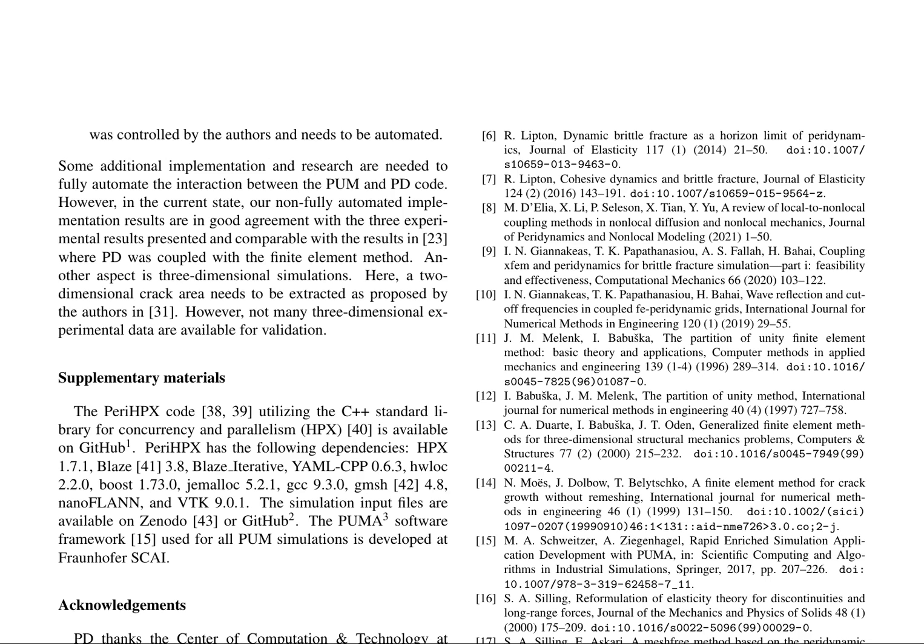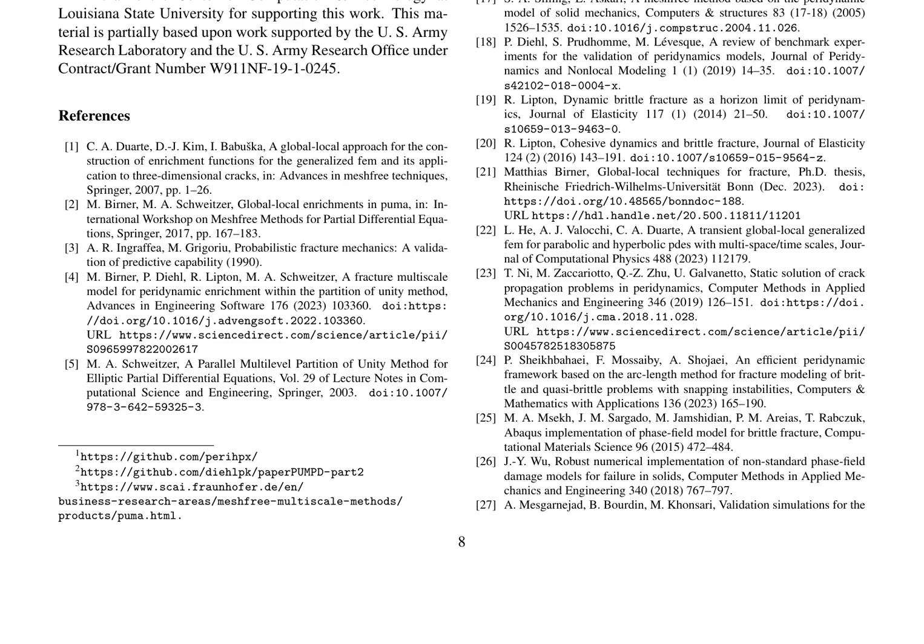Traditional finite element methods face challenges in modeling fracture, including limitations in capturing non-local interactions and complex geometries. Peridynamics, a non-local, non-convex, and dynamic approach, addresses these limitations by modeling material failure through bond breakage. However, coupling PD with traditional finite element methods has been a significant challenge. The proposed model resolves this by using the PUM to couple PD with the finite element method, enabling a more accurate representation of crack growth and failure.